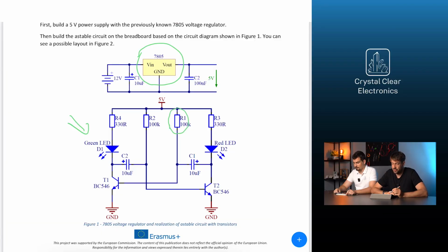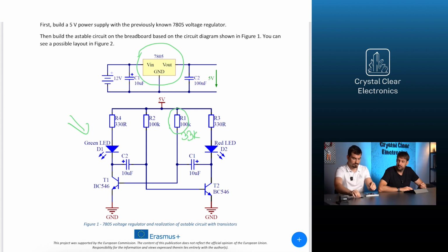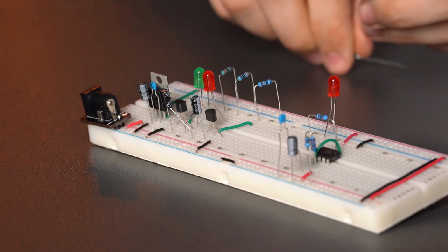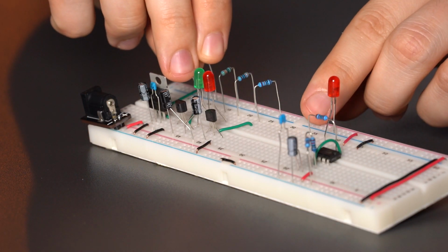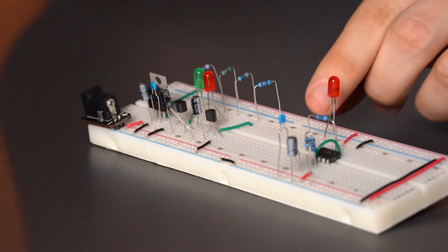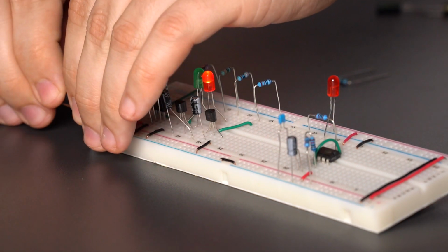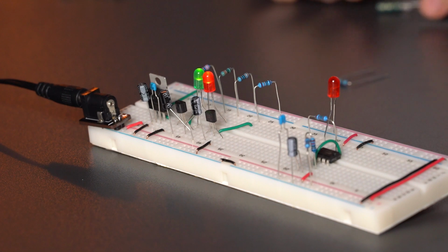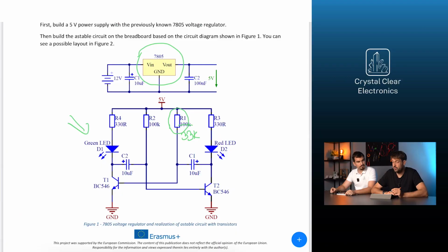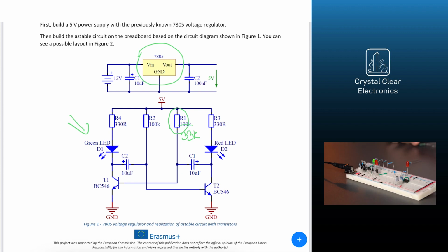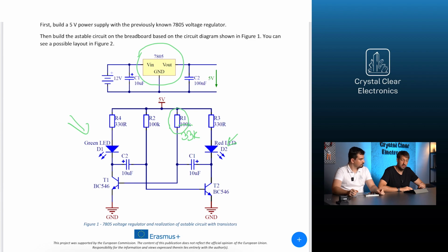First, replace the R1 resistor with 33 kilo-ohms. After the power is turned back on, the LEDs are blinking asymmetrically. The D2 LED will light for a shorter time than the other. The same happens with LED D1 when you replace R2 while R1 is 100 kilo-ohms.